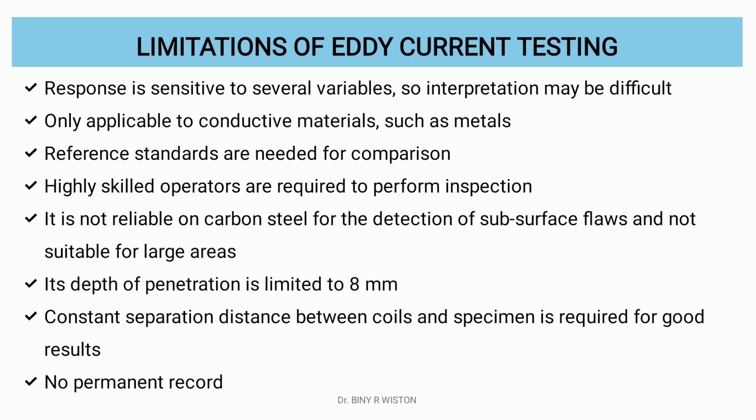Highly skilled operators are required to perform inspection. It is not reliable on carbon steel for detection of subsurface flaws and not suitable for large areas. Its depth of penetration is limited to 8 mm. No permanent record is available in eddy current testing.